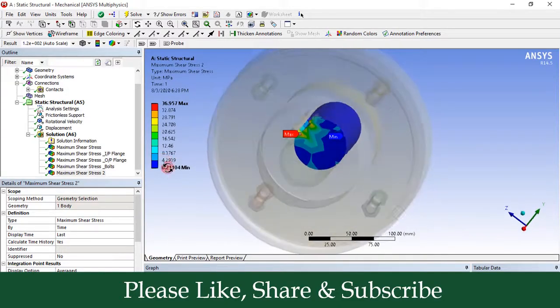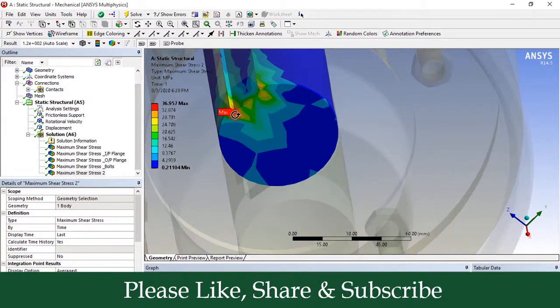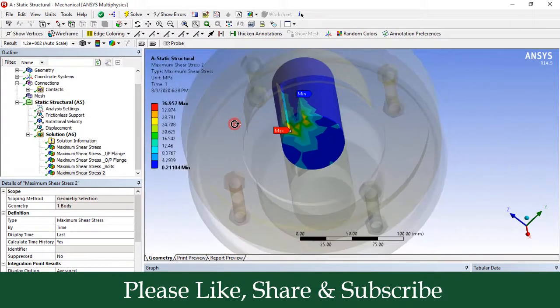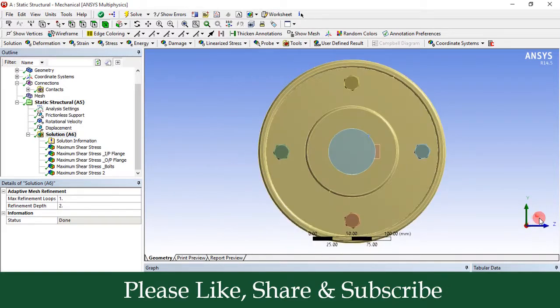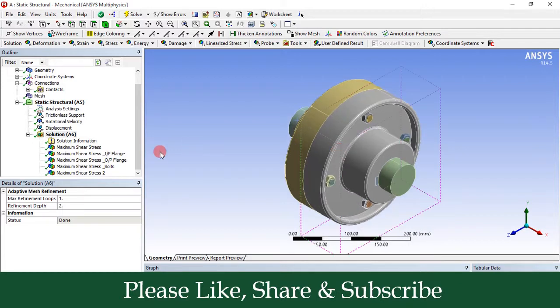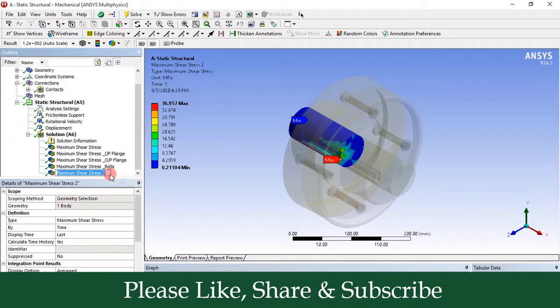As you can see here, this is the point of maximum shear stress where the slot is made in the shaft for the keyway. So this is just because of the stress concentration in the shaft. Now similarly, you can check the maximum shear stress in the output shaft. Before that, rename this. So this is the maximum shear stress parameter for input shaft.